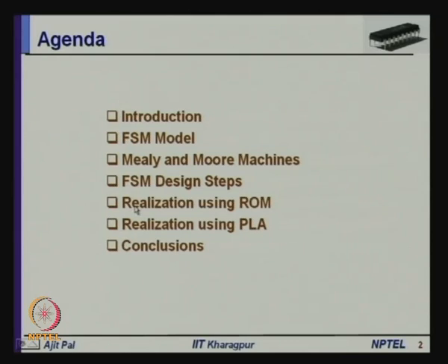Then I shall discuss realization of finite state machine using read only memory. As you know, read only memory can be used to realize combinational circuit. Similarly, we shall use programmable logic array for the realization of finite state machine. I shall discuss about them. Then I shall conclude my lecture with some concluding remarks.